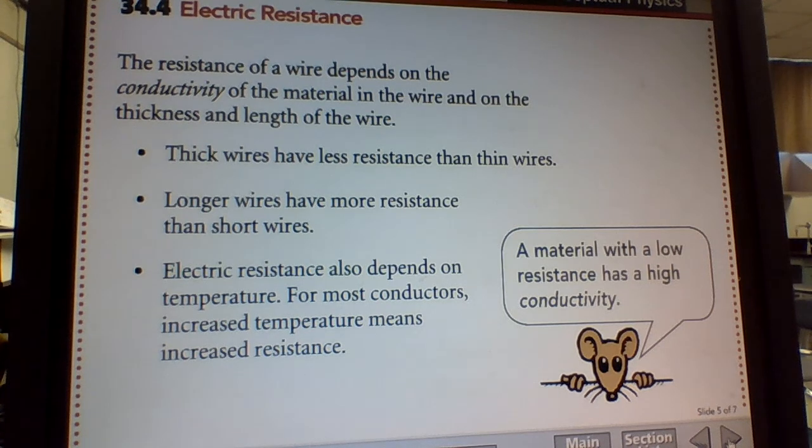So if you ever run very, very long wires in your speaker systems, say you're wiring a speaker system in your house, you want to use as little wire as you possibly can. Try not to make the runs super long. If you do make them super long, make sure you're using much thicker wires, a smaller gauge wire. But anyway, smaller number.